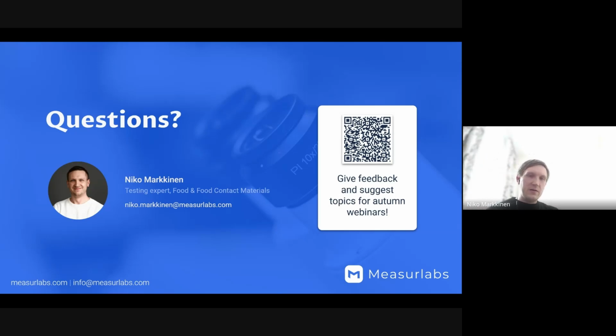And there are several different ways you can do it. You can measure a test piece, its dimensions, and knowing its thickness and its mass, you can calculate how much material you have. Oh, sorry. Well, you don't have to know the mass even. You just need to know the surface area and the mass. And then based on the residual content, you can calculate the migration there. Or if you know the thickness of the material and you know the density and you know the residual content, just using those three values, I believe you can do these simple calculations.